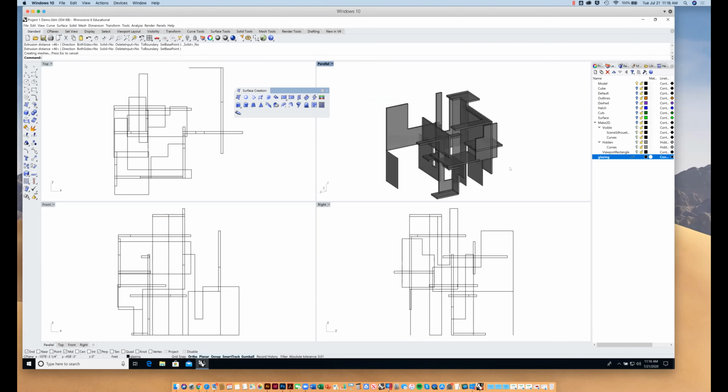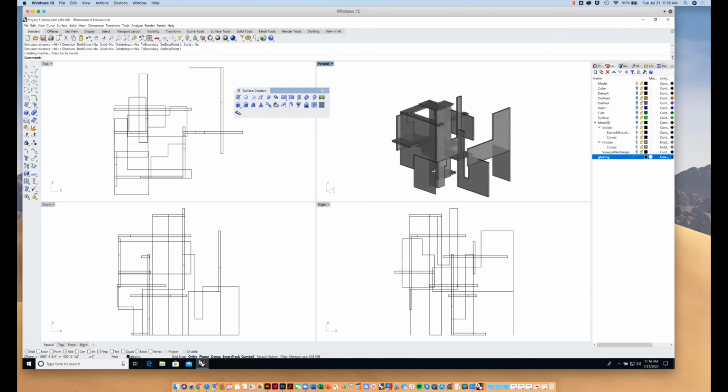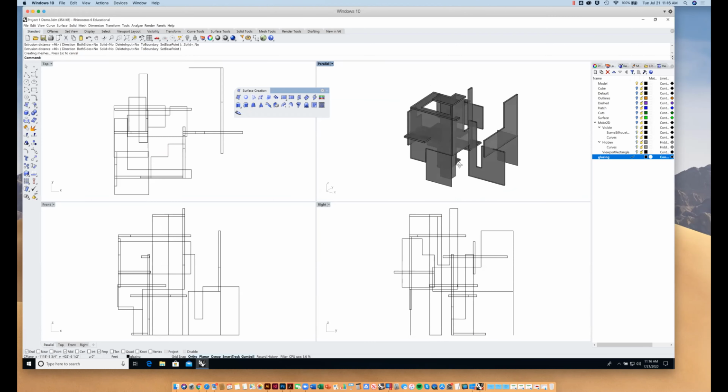And so what I'm doing is I'm just making surfaces without any thickness this time. And I'm going to bring those into my Revit model as well. And I'm going to make those glass with some mullions, right? The little window panes. Okay. And so now that I have 1, 2, 3, 4 instances of those, I think I'm going to show you guys how to then export this model out of Rhino and into Revit.